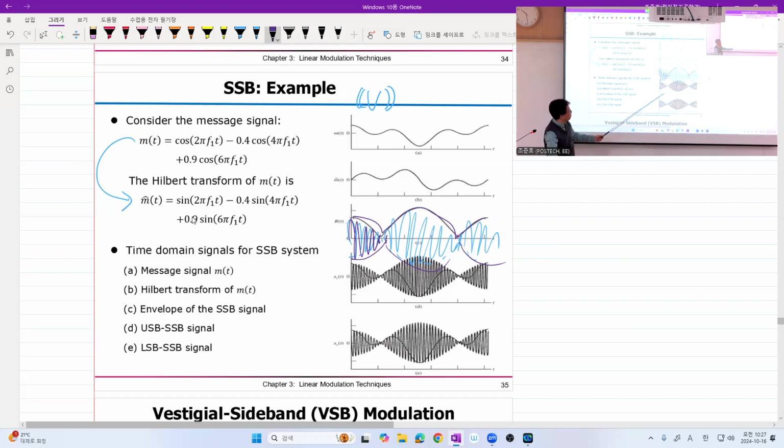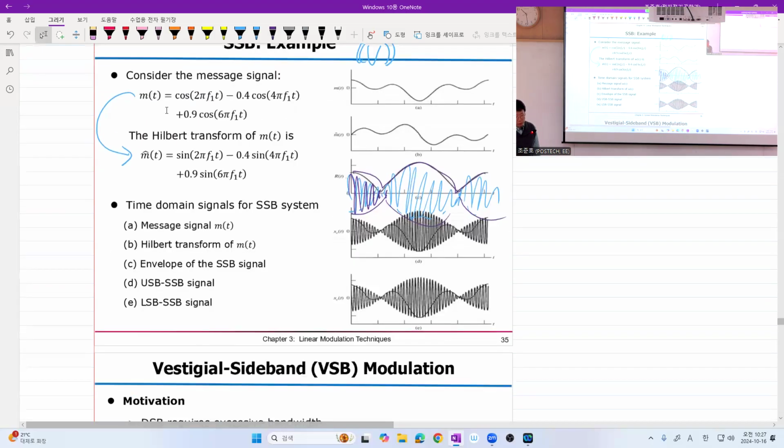The envelope looks the same, but if you look carefully, you have a difference in the phase and also in the zero crossing distances between two points. Got it? The reason is that now the SSB signal has non-zero quadrature components too.